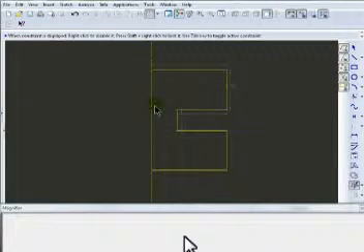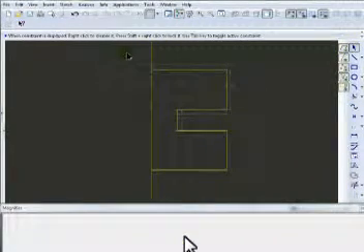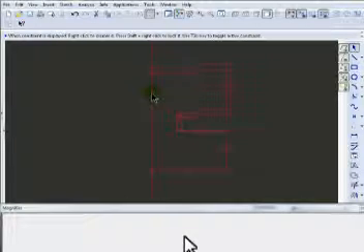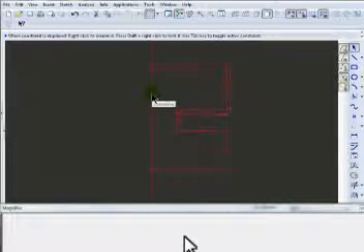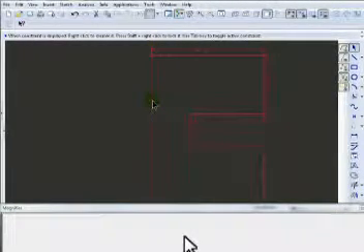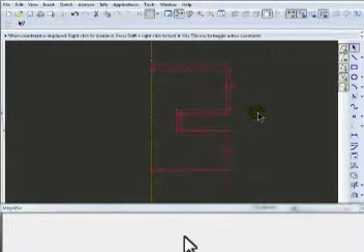center line. So we'll switch to select, drag a box around the geometry, select it. Now notice that you have a center line here that you selected, but you don't really need to select it. So to unselect it, hold the Control key down and left mouse click. Now to select something, you do the same thing. This toggles between select and unselect. So it's the Control key, while you're holding the Control key down, a left mouse button.